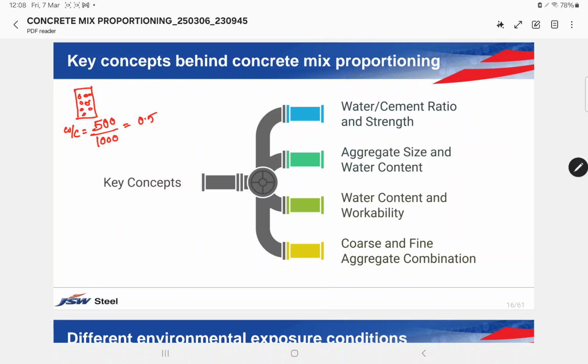So this is my drawing. As time passes, the cement will start to hydrate. Now just remember that the volume of products of hydration will be more than the initial volume of cement grains. What I mean is, if these red dots are my cement grains, after the hydration happens, some hydrated products will be formed, and those products will have higher volume than the initial volume.